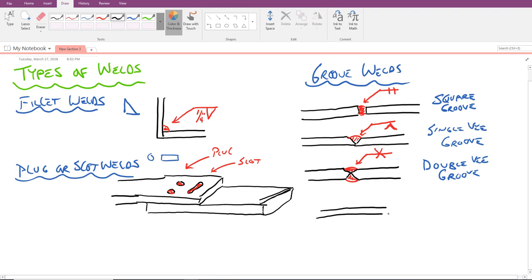And so if we had a plate down here and wanted to do one perpendicular there, this one would be a single bevel T. Again, T makes the shape, meaning perpendicular, but they do spell it T-E-E. And the symbol looks like that.